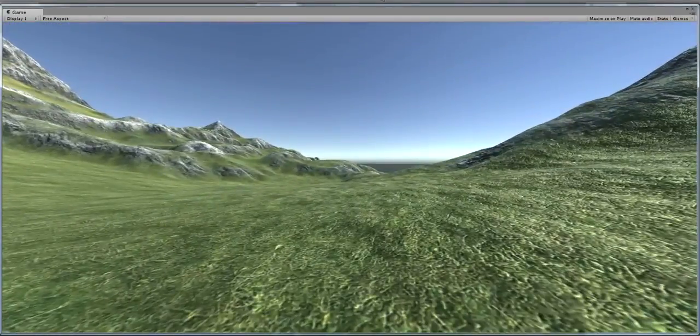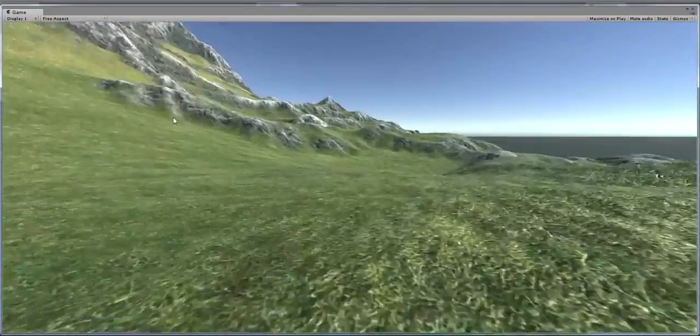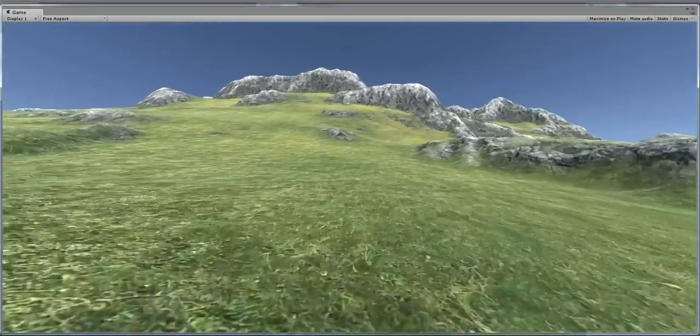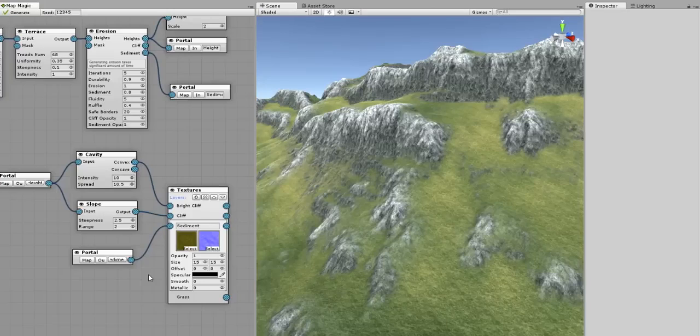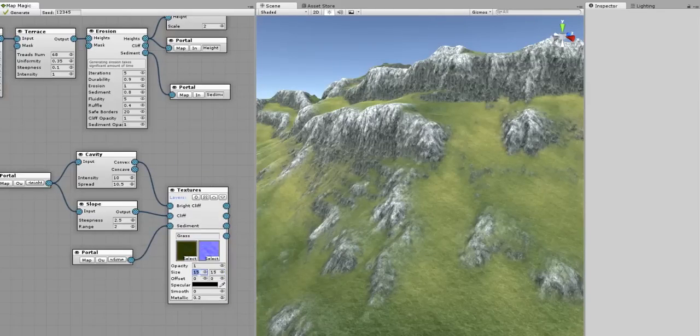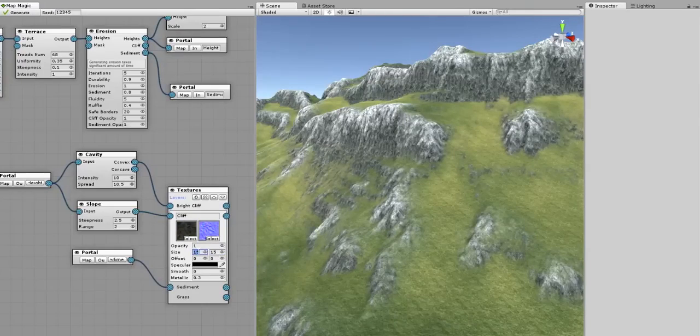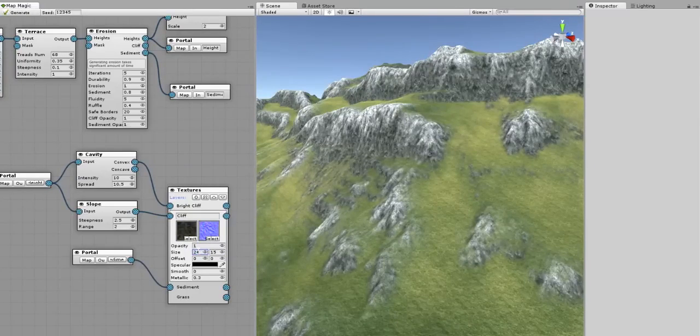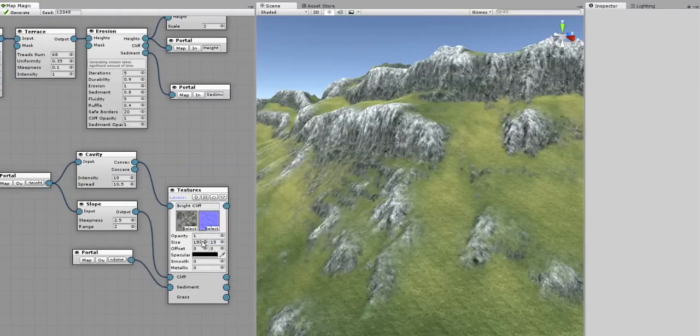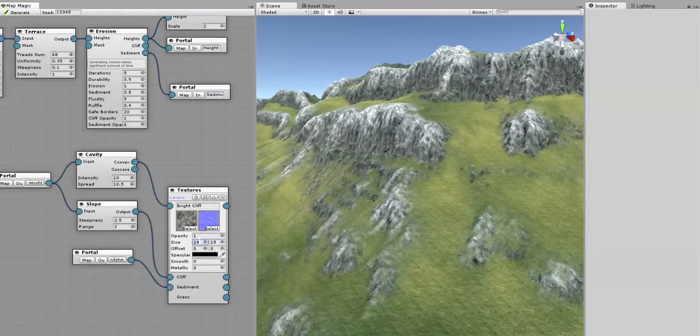And we're going to adjust the texture tile size. The grass looks too big and the cliffs are too small. I'll start with the texture size and set the grass size to 12. Well, it's better to use a power of 2 here to repeat a texture a whole number of times per terrain. It will make the seams between terrains invisible. But I'm afraid that 8 will be too little while 16 is too big, so I'm using a compromise. And I'll set 24 for the cliffs.